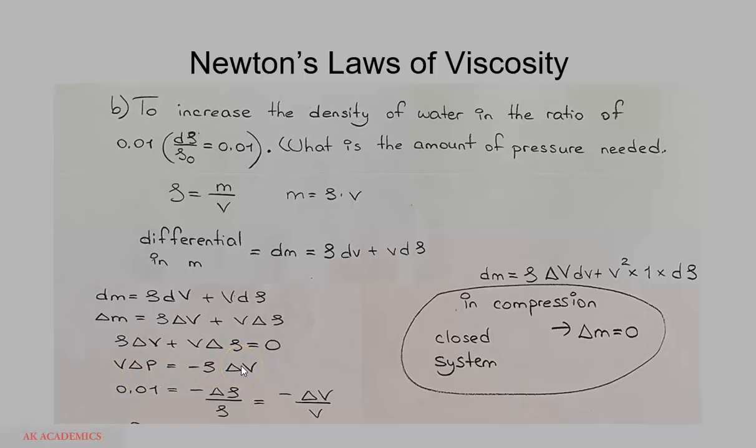Don't forget, what we're actually looking for is the ratio of the change in density with respect to the initial density, so we can easily find that here. This is going to be V multiplied by density. This is delta density. There is a mistake here. This is supposed to be delta density, not delta P. So if you rearrange these and make delta density divided by density the subject of the formula, it will be equal to delta density over density equal to minus delta V over V. If you just carry out this rearrangement here, you're going to obtain these.